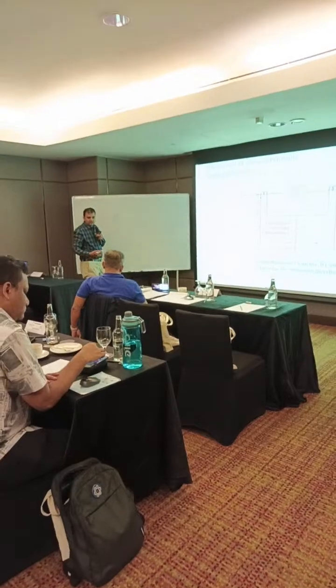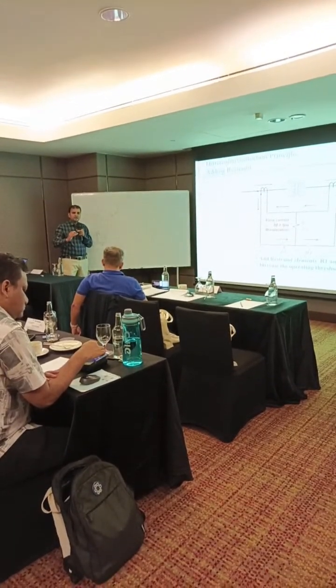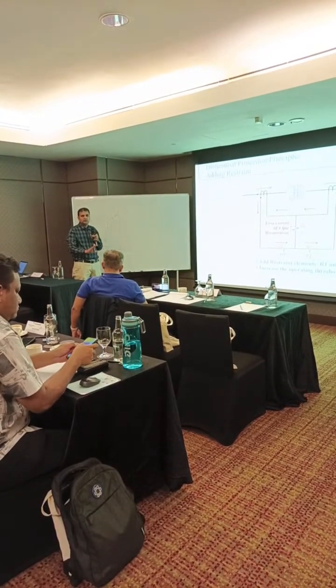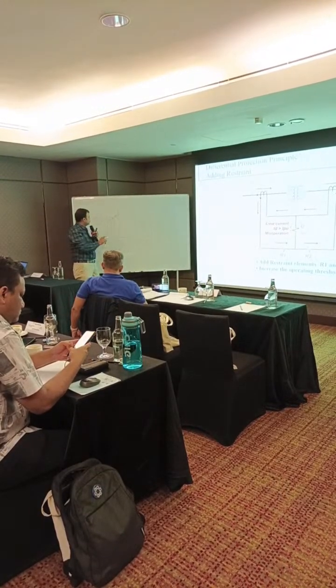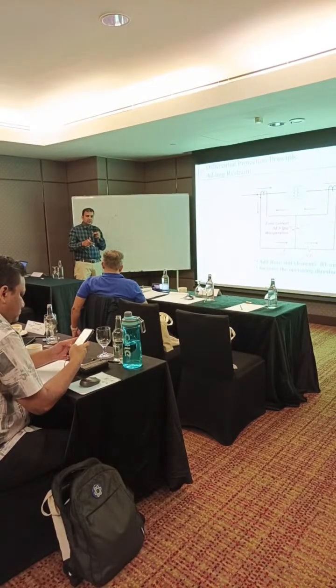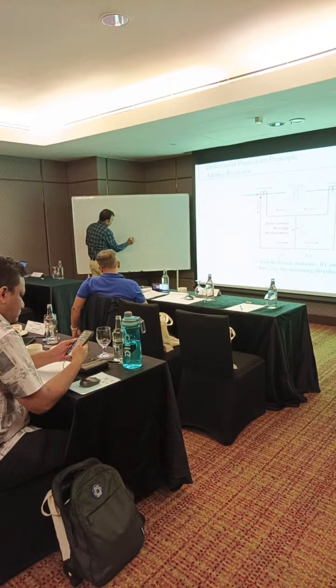How can we take it? You just increase the one side current, and when the differential trips, then stop and note down the both side current what you have injected. Then again inject the same current and hold that value and measure the IR and ID value.